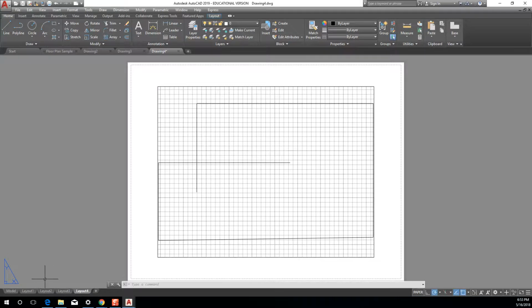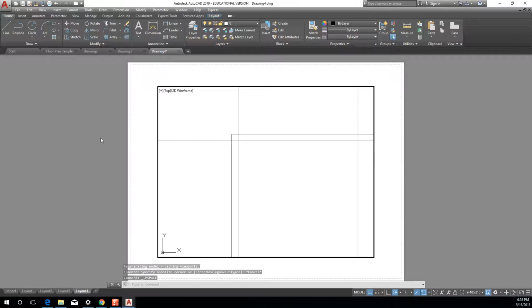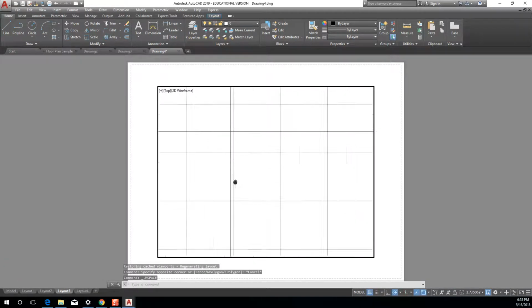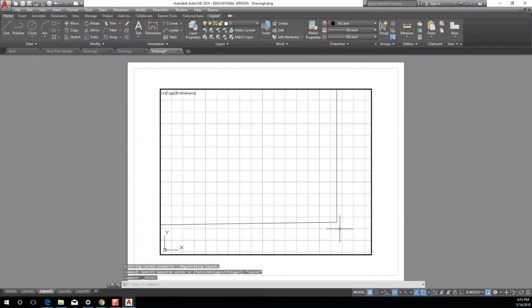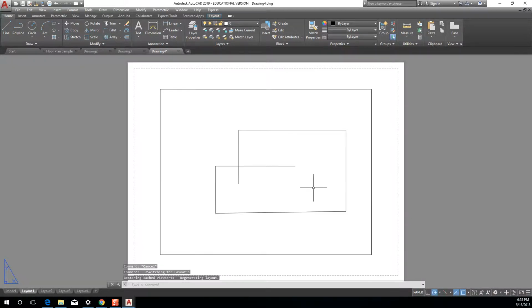So it makes sense that I could have 1, 2, 3, 4 different tabs where I can somewhat zoom into different areas in a drawing, right? There's the corner, okay? Maybe on this drawing, I want to capture this crossing. Maybe on this drawing, I want to zoom into the corner here, right? And maybe on this drawing, I want to view the entire thing, which is what I'm doing, okay? But again, in model space we draw, and in paper space we scale and print, okay?